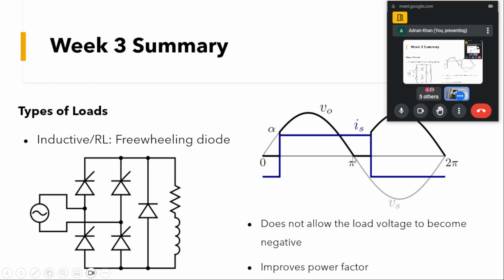So up to this point these devices are conducting, but as soon as the source becomes negative, in case of this inductance the output voltage was negative. But as soon as the output voltage will be negative, you can see that this diode will be forward biased, and this load will get shorted because of this diode, and it will provide a path.